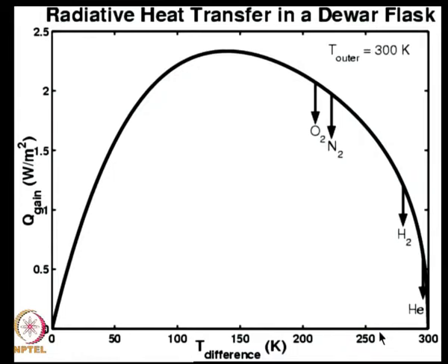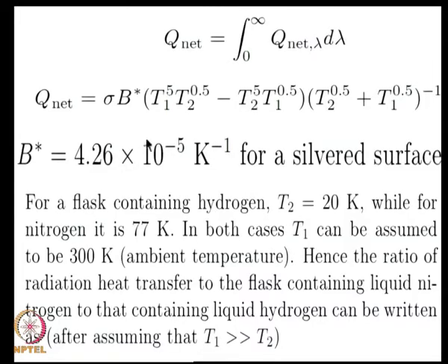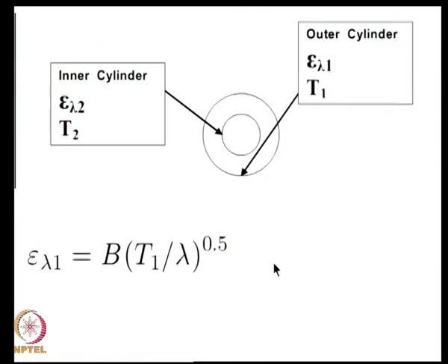And this can only be explained by the fact that the relation between heat transfer and temperature in the case of radiated heat transfer is quite complicated, especially when the two surfaces are not gray, but metals, and because of the spectral variation of emissivity with temperature and wavelength, we get an unusual result.